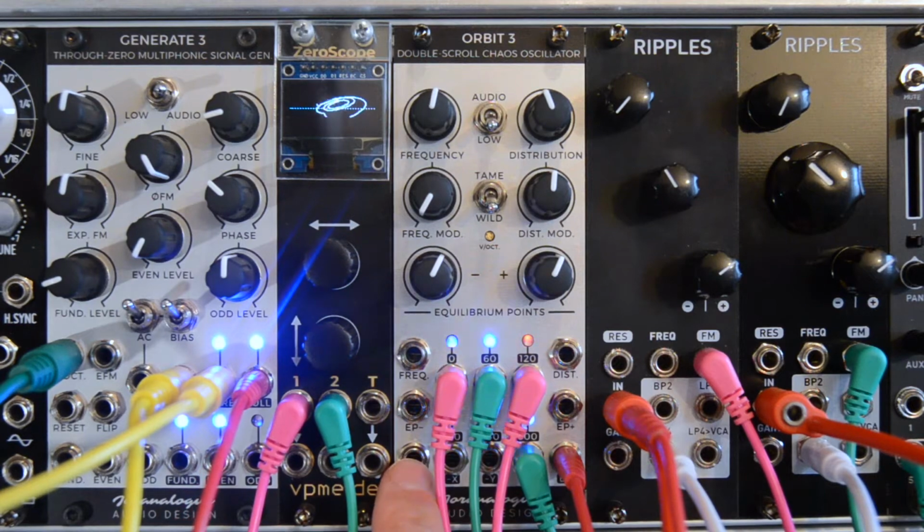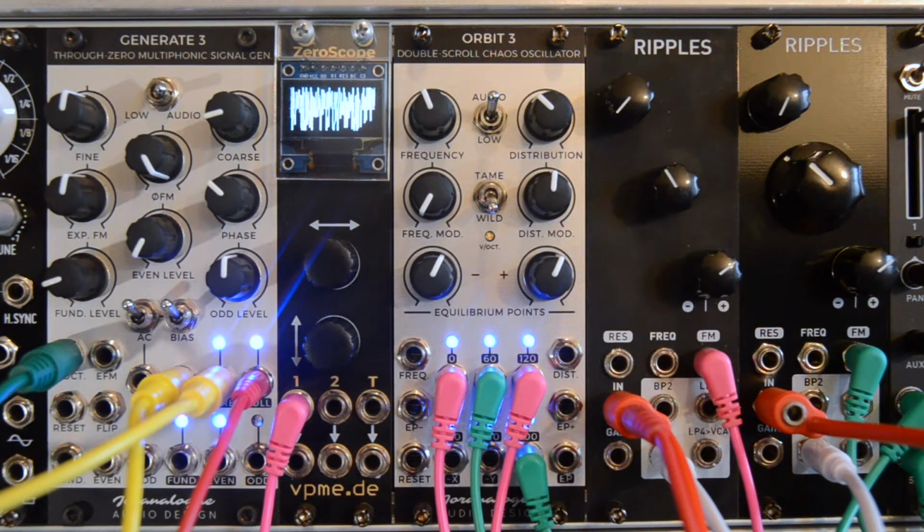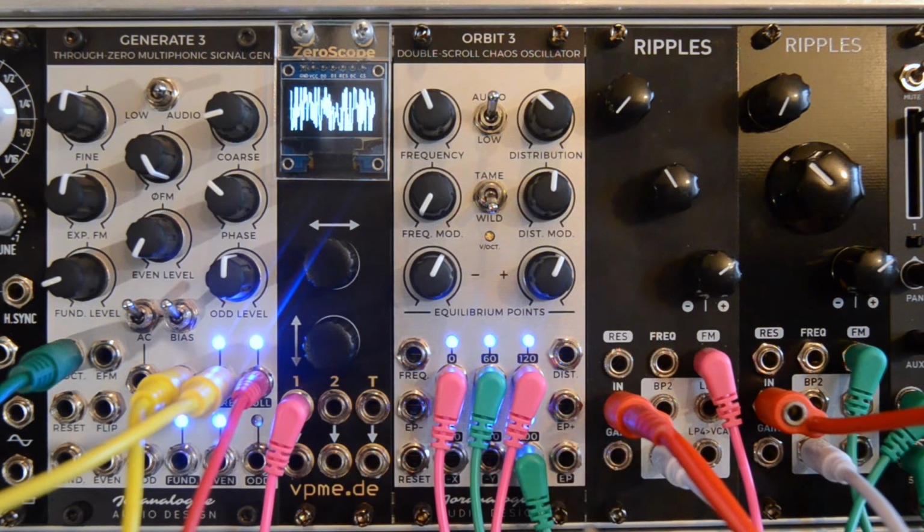The reset input on Orbit 3 is cleverly designed and it reacts to about any signal you send into it. You can use LFOs, VCOs, gates or triggers to force Orbit 3 to reset its oscillations. This is useful to create typical hard sync sounds or to synchronize Orbit 3 in low mode to the tempo of your system. You can even use this input to self-patch Orbit 3 to produce stable oscillations at any setting. This patch is explained in the manual, by the way.